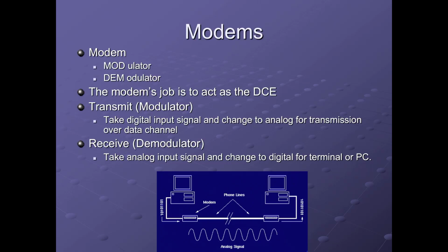And so it's impressing upon the analog signal the information, the ones and zeros. And when it does that in the transmit direction, it's what's called modulating the carrier. And when it's receiving the signal as the receiver, it's demodulating the signal. So in the transmit direction, it's impressing the information upon the carrier. In the receive direction, it's decoding or removing the information from the modulated carrier and delivering the high-low signal to the receiving terminal. And so that's called a modulator-demodulator, or it's shortened to give you the term modem. And that's where the term modem comes from, modulator-demodulator.